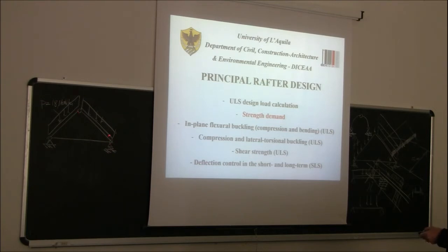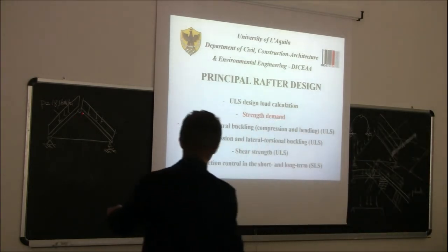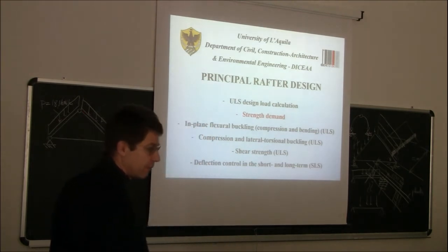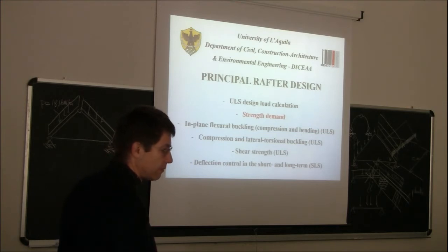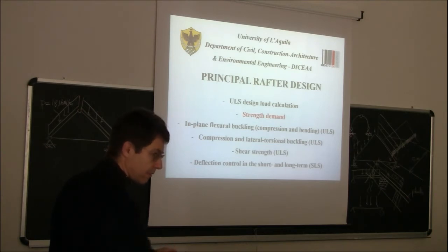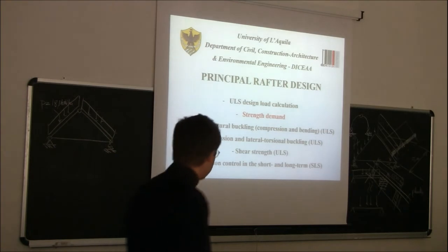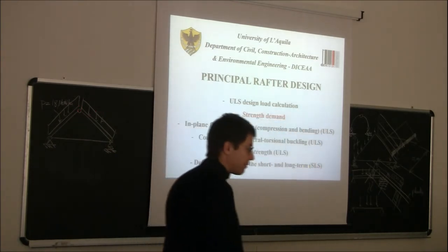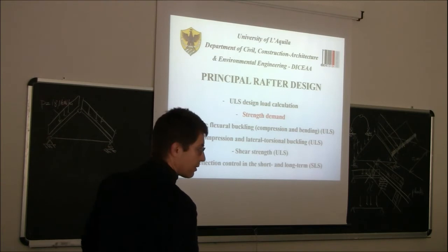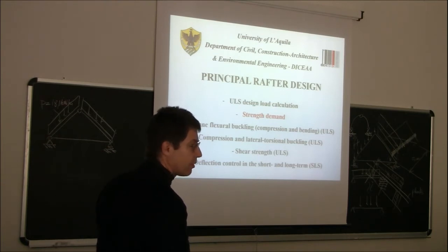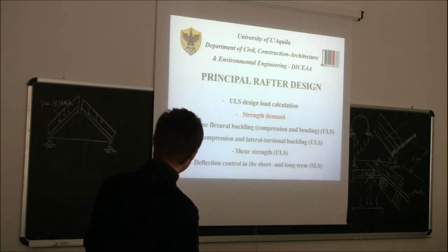Then we have another internal pin. Are you sure that this takes away 3 degrees of freedom? Two degrees of freedom, this one, because this allows only the rotation. Yes. So 2 here, then 2 here, 2 here, 6. So 9 minus 6 equals 3, and then we have the external restraint. This one.